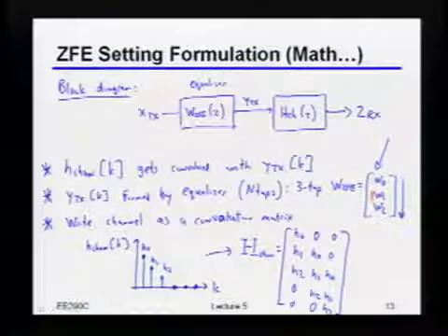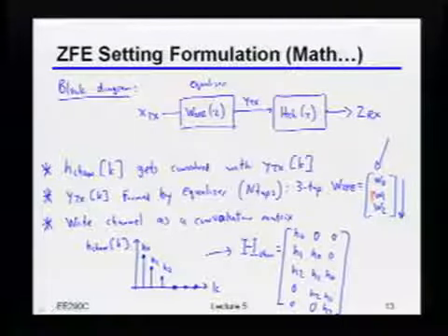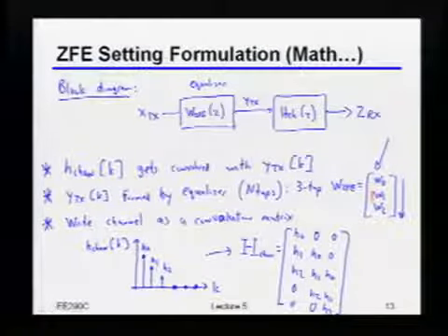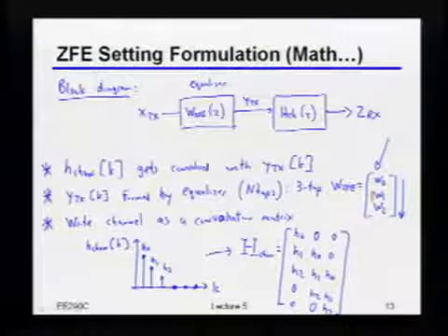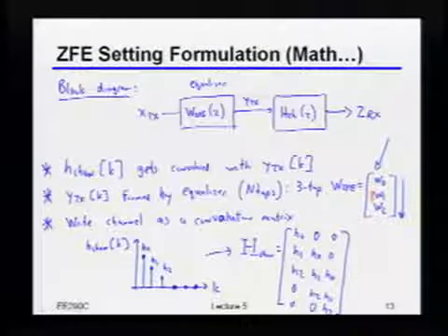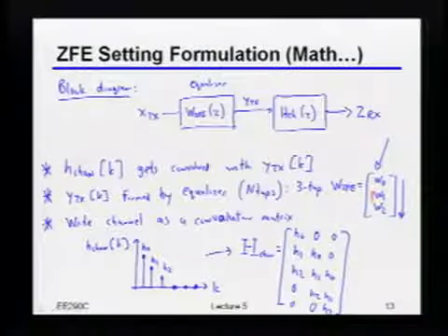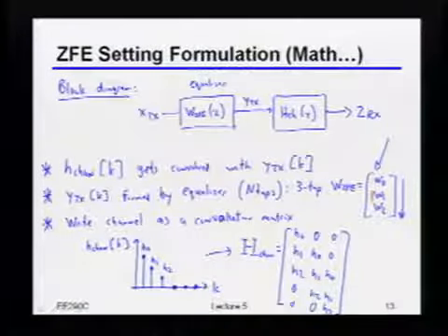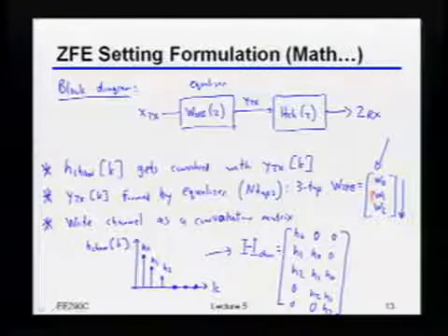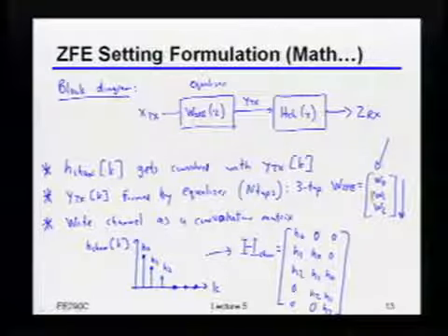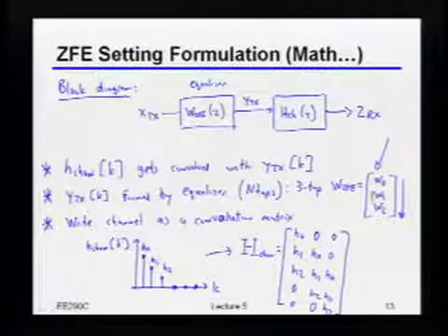So the sampling rate here is my bit rate. In other words, if I'm signaling at 10 gigabits per second, I'm sampling at 10 gigasamples per second. Okay. Does that make sense? Yeah. But is that enough to represent the channel well enough? Ah, okay. That's a great question. We're actually going to talk about that a little bit more later. From the standpoint of the data, that's sufficient to get the Nyquist frequency of the data. Okay, because if I have 10 gigabits per second, the fastest the data could be doing is 5 gigahertz.